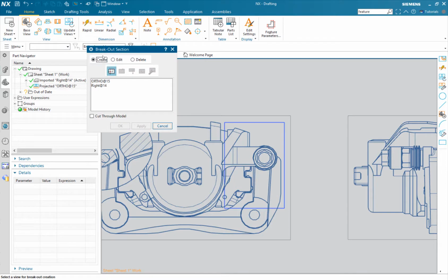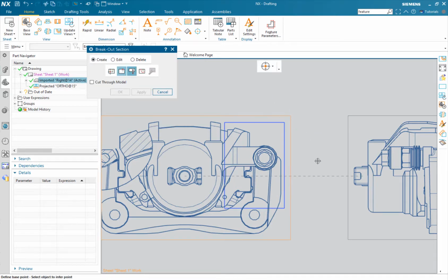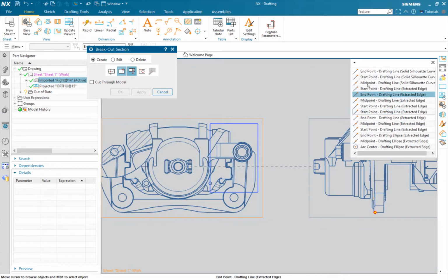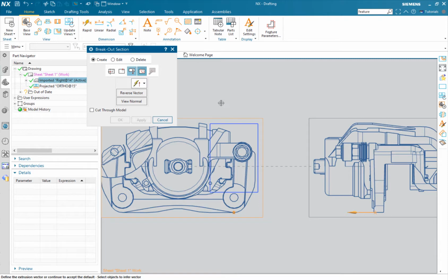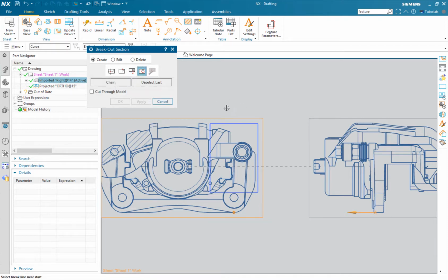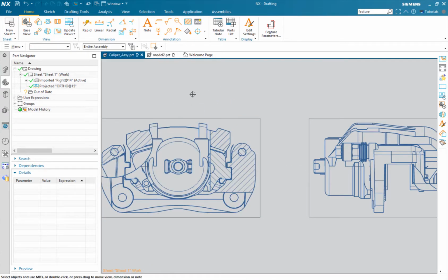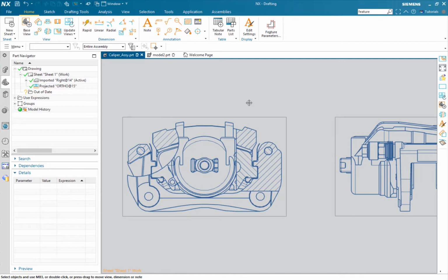We'll go to Breakout Section View, choose the view, then how far in do we want to go? So I'll choose that point, middle click to advance, then I'm just choosing that rectangle and finish. So using the breakout section is really easy when you're using the sketch inside of the view. And here's the added bonus. Did you notice two breakout sections in one view? Pretty nice tool.